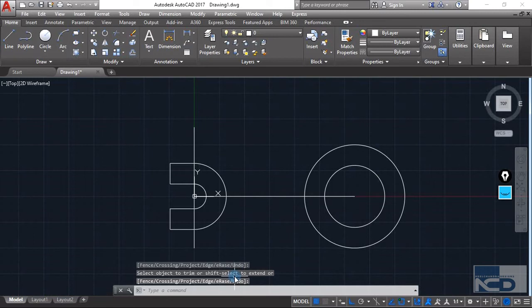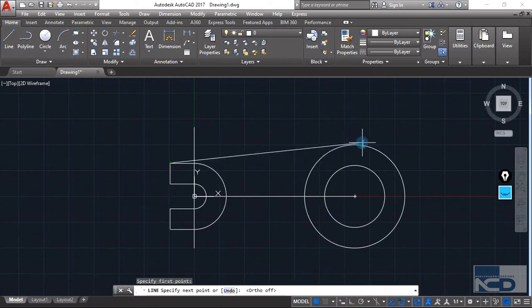So now there we go, we have the two sections ready over here on the two endpoints. Now we have a simple task: we just have to attach a line from this endpoint to the tangent of this circle. For that, we again go for this line command. Just select this endpoint and switch off this auto, and you will grab the tangent over here. It's just like this.